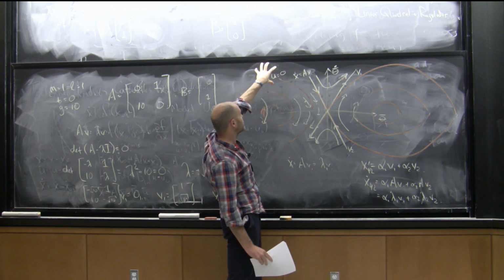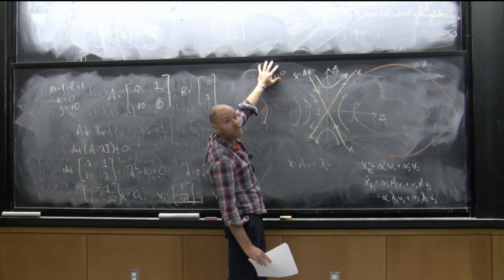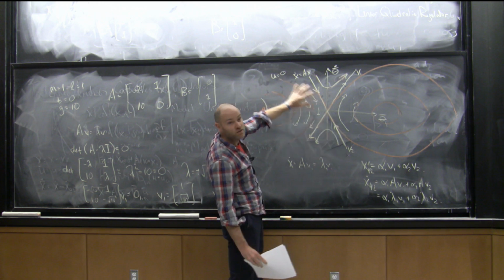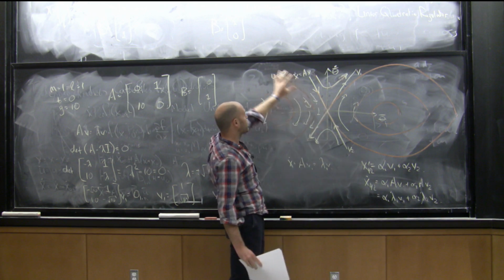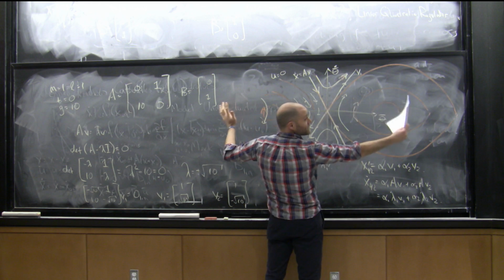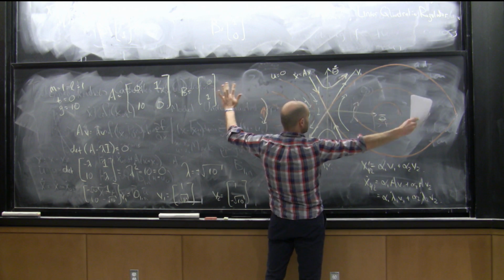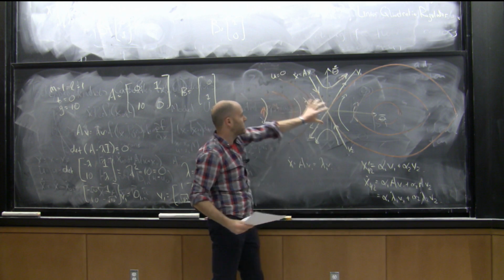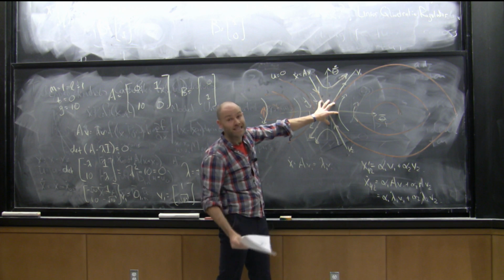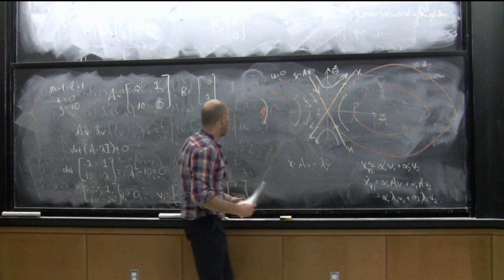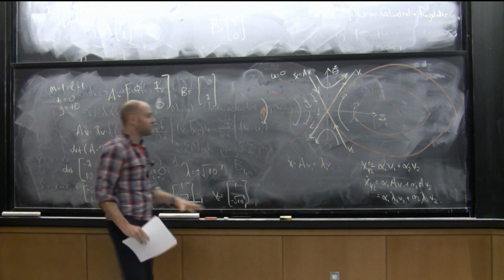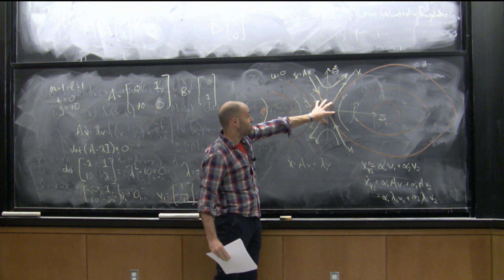And you can't do control design of this part of state space by itself, because anything you do is just going to dump into this part of state space. You can't ignore the rest of the world. You have to somehow jointly do an analysis of a piecewise affine approximation. Sure, you can make an approximation of it, but there's something special about linearizing around a fixed point, because the dynamics actually come out linear. The Taylor expansion comes out linear, not affine.